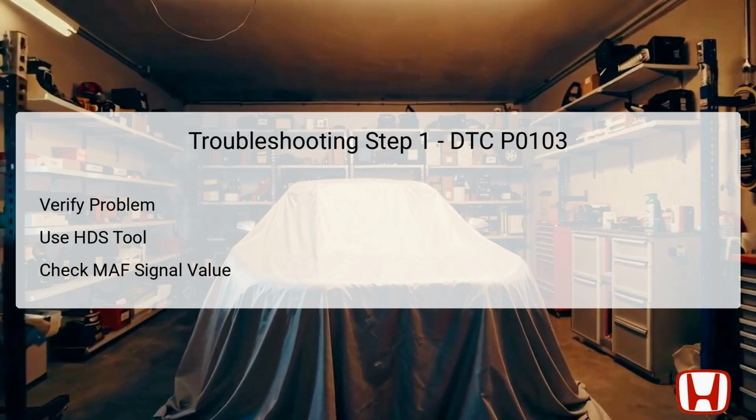Once the system is ready, check the MAF sensor's voltage signal with the HDS tool. The key reading to observe is whether the signal exceeds 4.89 volts. If it does match the threshold, the issue is confirmed, and you can proceed to the next troubleshooting step. However, if the readings do not match, intermittent faults may be present, such as poor connections or intermittent failures.